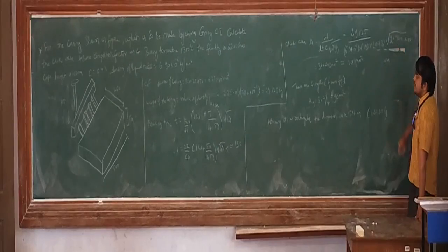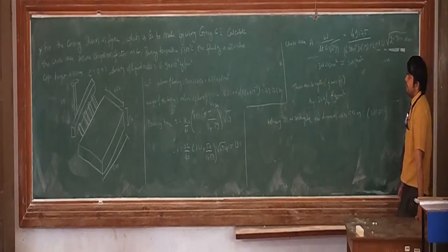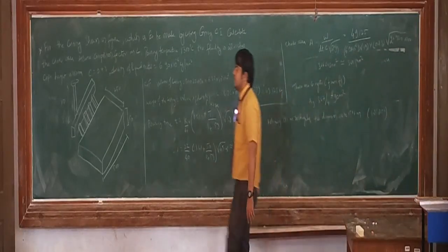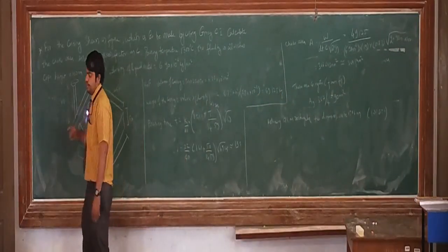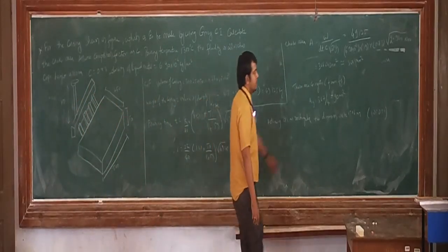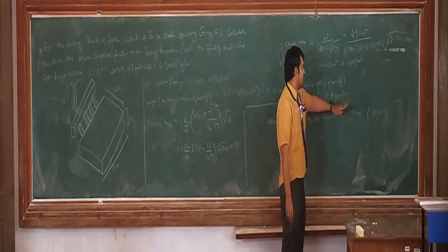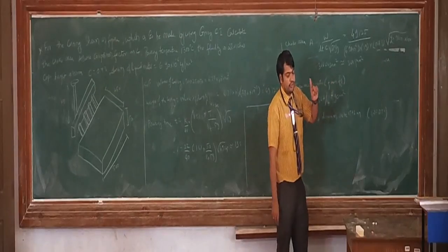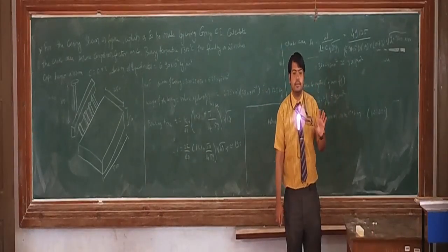Okay. Once that is done, we are going to substitute the values and we get it as 367 mm square. Once we found out this value, as there are 4 ingots, so here you can see 1, 2, 3, 4. 4 ingots are there. Because of that reason, we are dividing this total choke area by 4. So it will be 90 mm square. So the area of cross section of each ingot is 90 mm square.